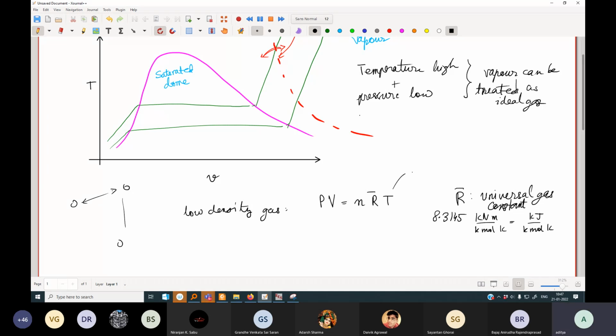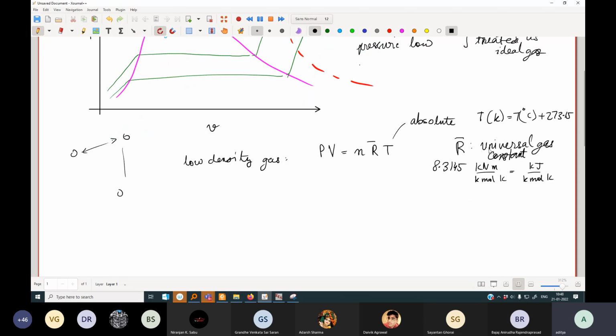And the temperature over here is absolute temperature. It's not in degrees Celsius, it is absolute. Many people will make this mistake, but you must remember that the temperature in Kelvin is temperature in degrees Celsius plus 273.15. Whenever you have division, multiplication of only T going on, you must use the absolute values. We will come to the actual justification when we deal with the temperature scale in the topic of entropy. The basis is quite involved, but for now, this is enough information for you.